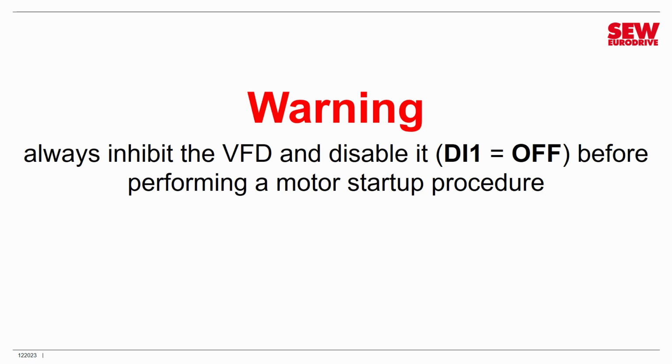Let me give you a warning that I gave you way back in the beginning of this class when we did our first motor startup. It is always a smart idea to disable your VFD by turning digital input 1 off and inhibit your VFD as well by activating the Safe Torque Off feature. So in other words, remove 24 volts from Safe Torque Off Plus and remove ground from Safe Torque Off Minus.